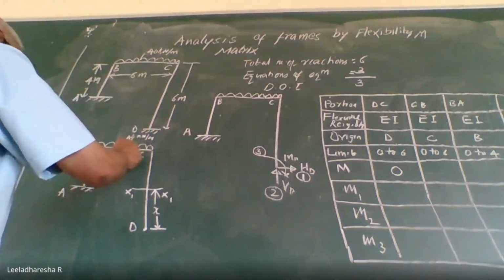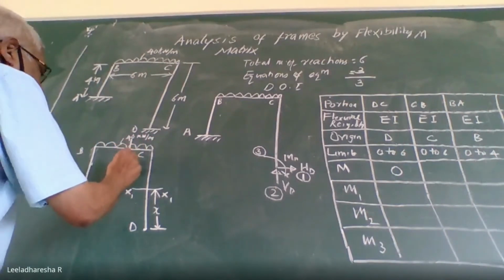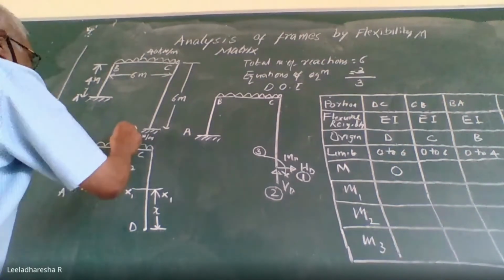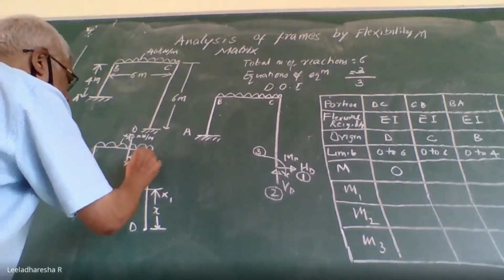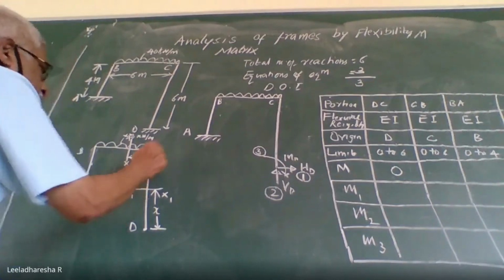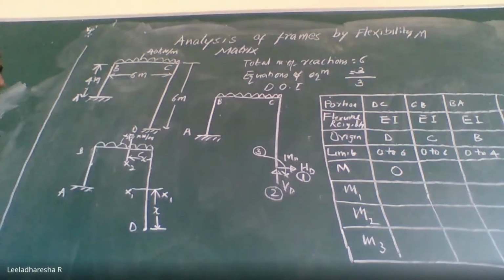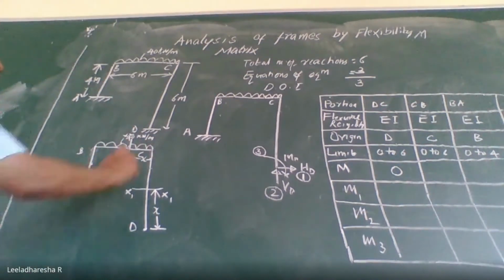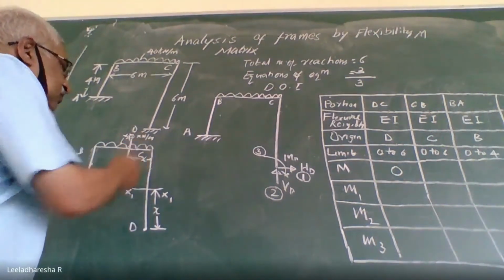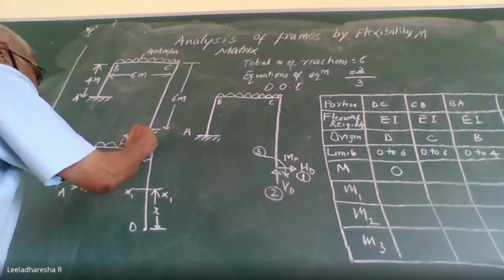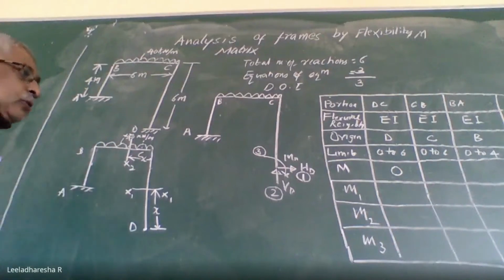Next, consider origin C and the beam BC. Again, select a section, say X2, X2 at a distance X from the origin. So now, in this portion, uniformly distributed load is acting. So what is the bending moment at this particular portion? It is sagging bending moment. W into X is the load, and this load acts exactly at the center of X, that is X by 2.